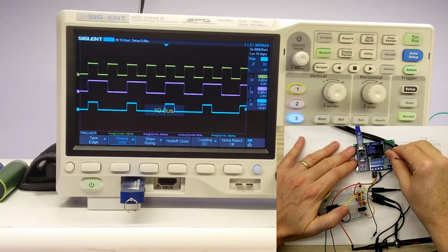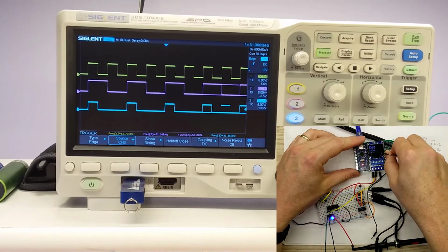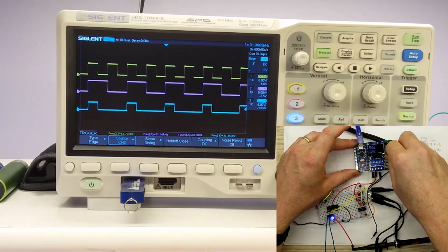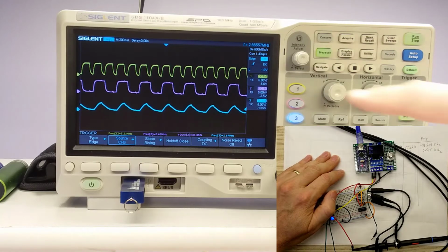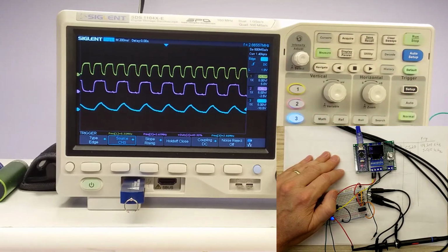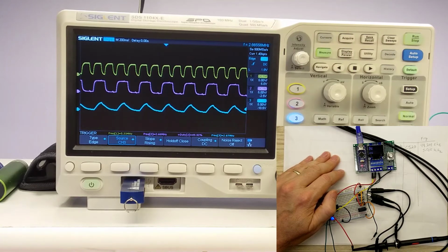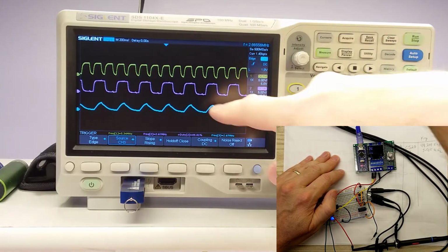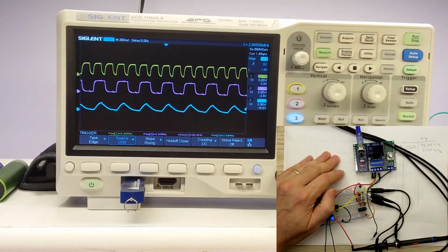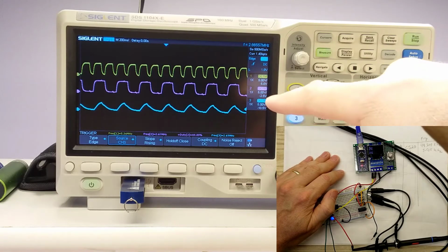So let's go ahead and ramp this up closer to 1 or 2 megahertz. Now we've got our primary frequency at about 5.3 megahertz on the yellow, and then the pink is exactly half of that, and then the blue is our output. And as you can see, it's actually keeping up pretty well. I mean, it doesn't have a nice little square wave. It's much more of a little triangle, but in all practical purposes, I would say that is keeping up well within the specs of the scope.